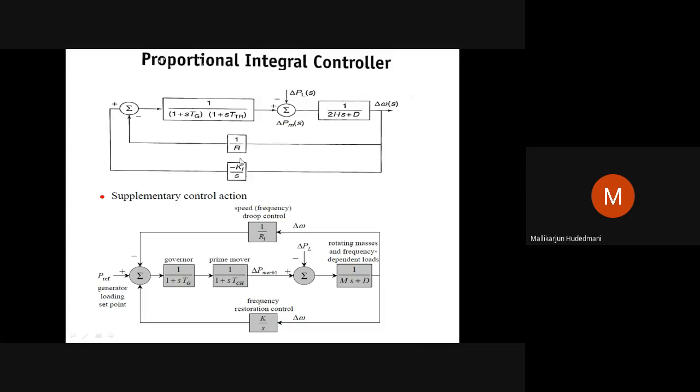Now, what is this exactly doing? This is taking the error. This is going to amplify the error, with a gain of KI, like a K over here. Then add it up and integrate it. Integrating means accumulate those things, amplify, integrate, and get the set point revision here. That set point revision and the actual droop by power calculation together modify the input to the governor turbine system. These two are multiplied together, a simplified block here. So this is the need for a proportional integral controller.